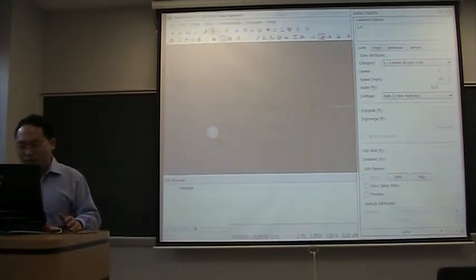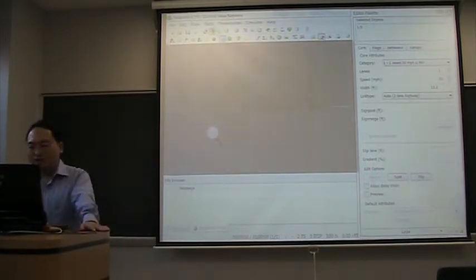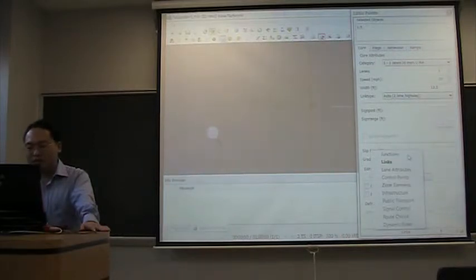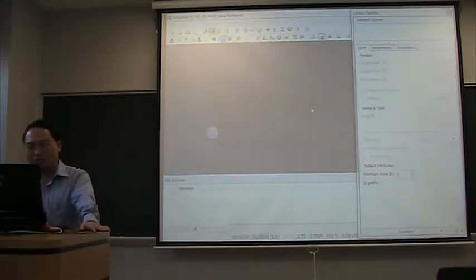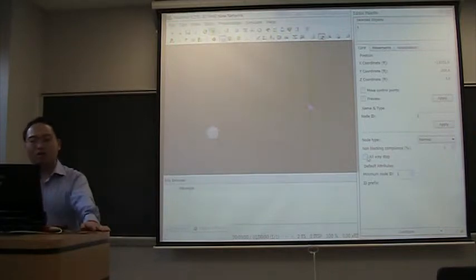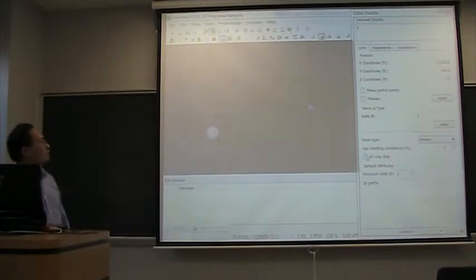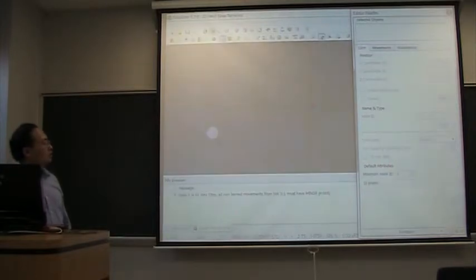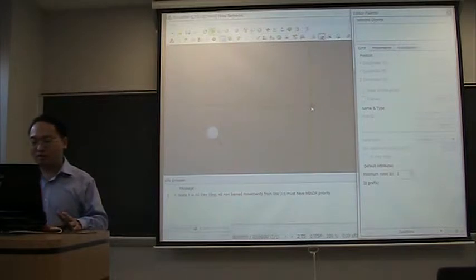Okay. So the next step is to create the 4-way stop signs. Let me go back to junctions and select the middle junction. And here is a checkbox called Always Stop. Just select it and save it. So at the center, we have already defined a stop sign.